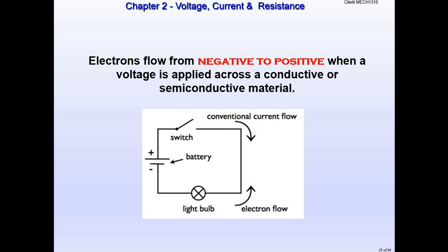That's why when you're jumping your car battery, the very last cable that you connect is the negative cable. If you already have that connected and you touch something else, that's where you can get hurt. Connect the negative last, because that's how electrons flow. So it sounds backwards, but it's because of how electrons really flow versus the conventional current flow method.